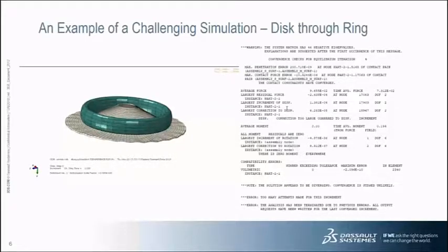If we look at the animation, we can see that this disk is wrinkling up, and so maybe I'm just not able to find static equilibrium. And that's really what is happening here. It's not too sensical, really, to do a simulation like this, which is quasi-static, without taking some special considerations if you're using a completely static procedure.